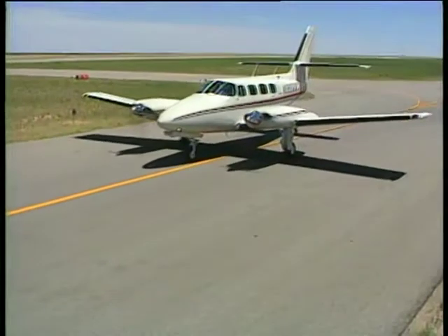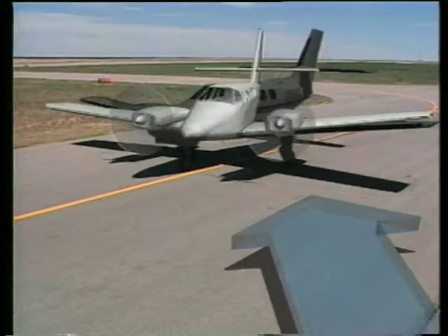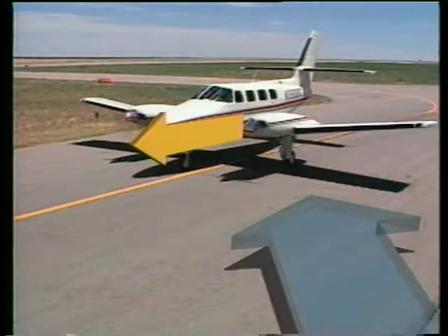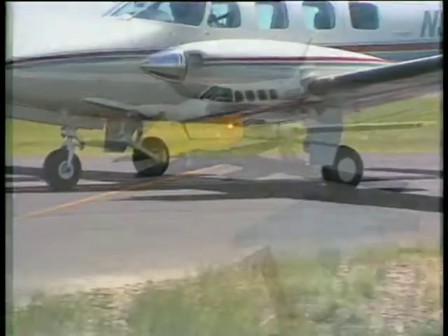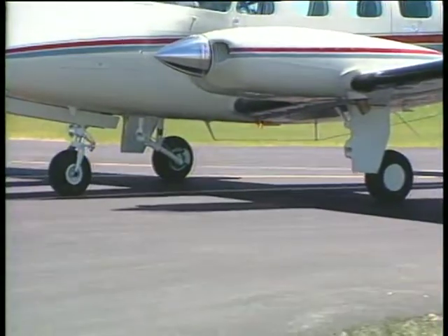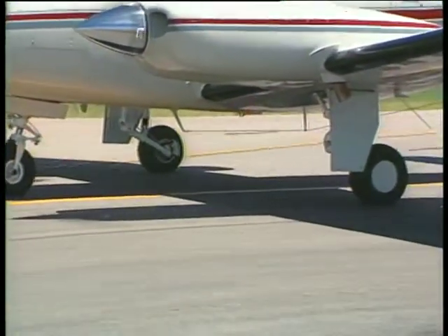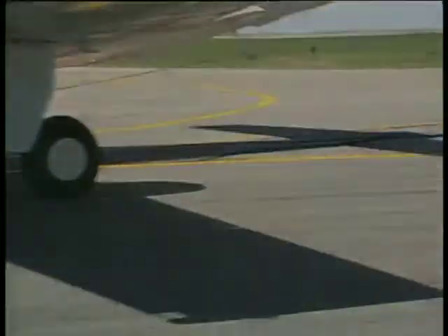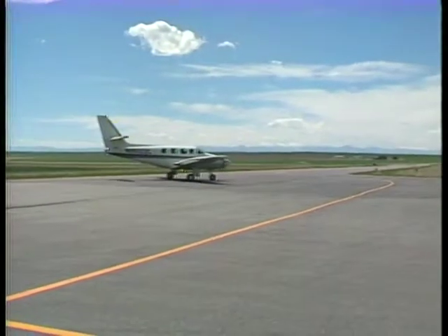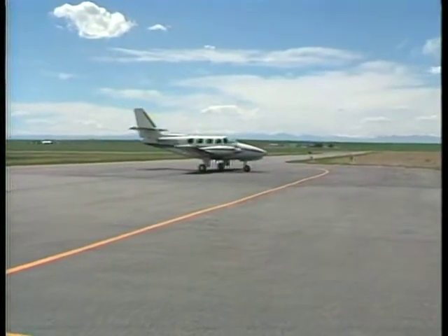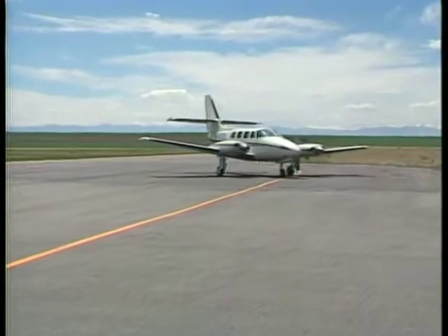In a strong crosswind, an airplane tends to weather vane into the wind. Differential power can help you maintain directional control by applying more power to the upwind engine to counteract the weather vaning tendency. Differential braking should be your last option for directional control, since it can increase wear and possibly overheat the brakes. Your pre-takeoff check in a multi-engine airplane is similar to that for a complex single-engine aircraft.